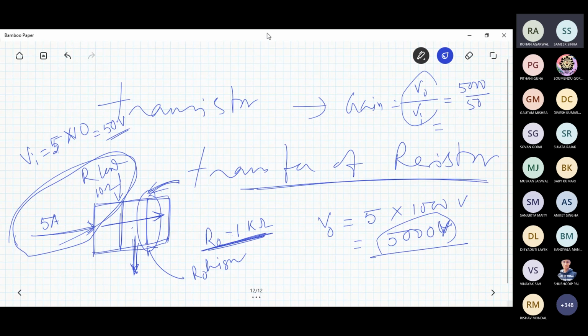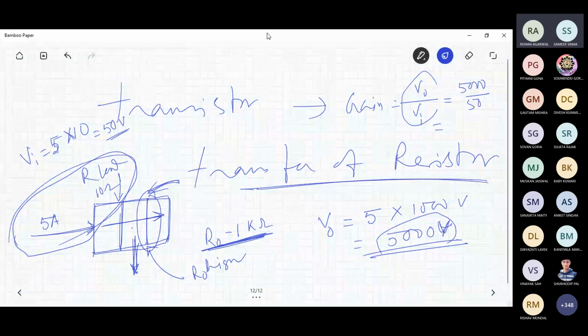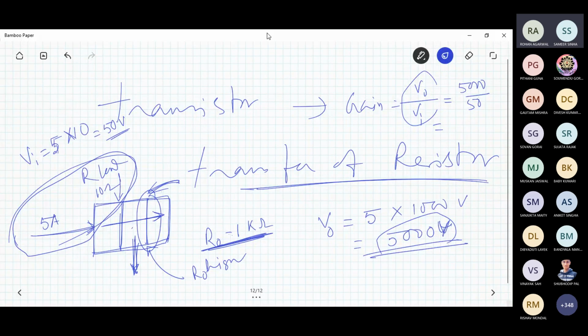Ohm's law is not really applicable here, because Ohm's law is applicable for linear devices. This transistor and PN junction are purely non-linear devices. I applied Ohm's law anyway because you are quite accustomed to that particular law, although except for a few conductors, it is nowhere applied. Just due to the change in the resistance level, there will be a change in the output voltage, and you get gain out of it due to the variation of the input and output.